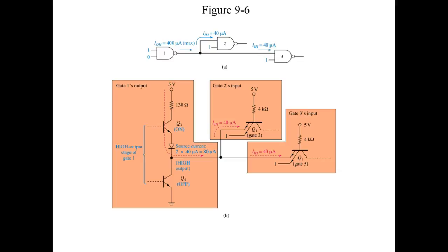And if you look, I don't know if they show the other or not. So this is sourcing. When we source, they don't show the rest of the current flow, but the current flow comes through here. We can't see the rest of the circuit. And then it comes up, and then it goes up through the source transistor. Now, the problem here is we put that 130 ohm resistor in there to protect the gate, right? You understand? Because if I was to accidentally ground this or ground it on purpose, we can literally connect the output of a TTL gate to circuit common and not hurt the gate because of that 130 ohm resistor. But right off the bat, we can't get 16 milliamps for a high, right? Down here, we don't have anything to go through. This is nothing but a transistor.